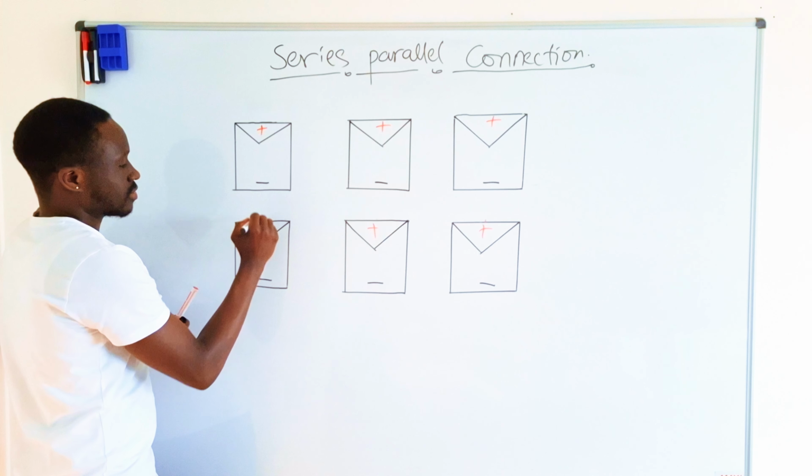Now, these two panels are connected in series. These ones are connected in series. These ones are connected in series. We have the positive out and a negative out. The positive, negative are combined, and that is the series connection. The same applies to these panels, okay? Now, how can we connect these panels in parallel? Okay? Can we connect these panels all in parallel?